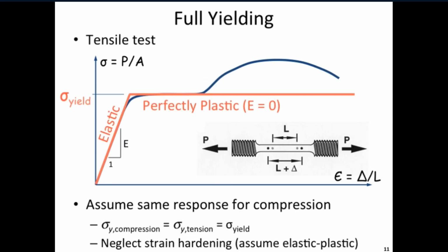So let's go all the way back to the beginning when we were performing tensile tests, or if we took a piece of structural steel, put it in a testing machine and stretched it, and we monitored its stress and strain properties. And what we would see is basically on the screen here, we'd start off with no load, and as we applied load, we'd get a nice linear response. And at some point, I'm going to track the blue curve here, we'd get some yielding, we'd have a yield plateau, then some strain hardening. Eventually, we'd reach the ultimate, and then we would rupture the material.